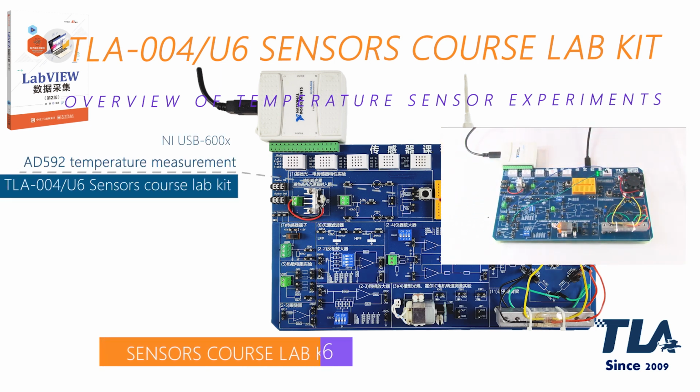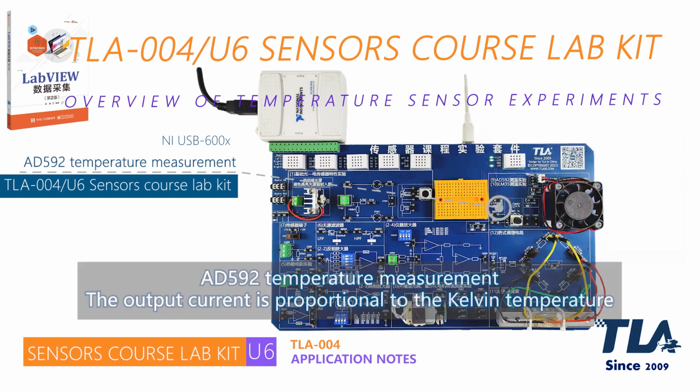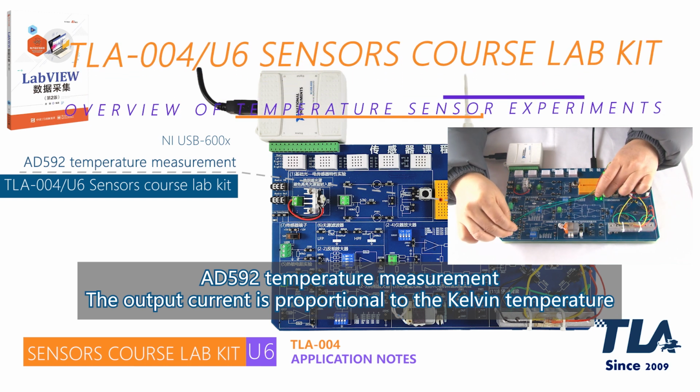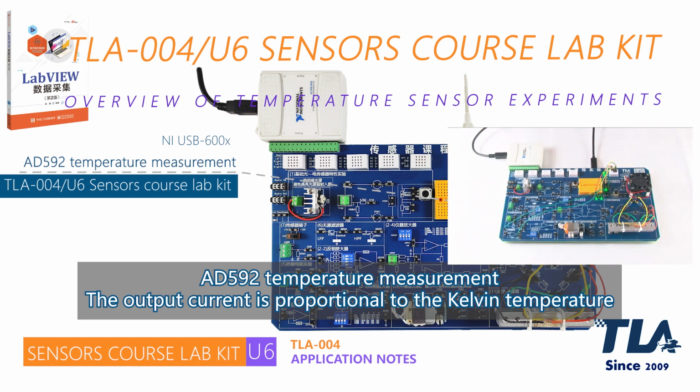Module 9 is an experimental module for temperature measurement with the integrated temperature sensor AD592. AD592 is one of the commonly used high-precision integrated temperature sensors, and its output current is linearly proportional to Kelvin temperature. Combined with the onboard heating and air cooling device, the experiment of temperature measurement and temperature PID control based on AD592 can be realized.